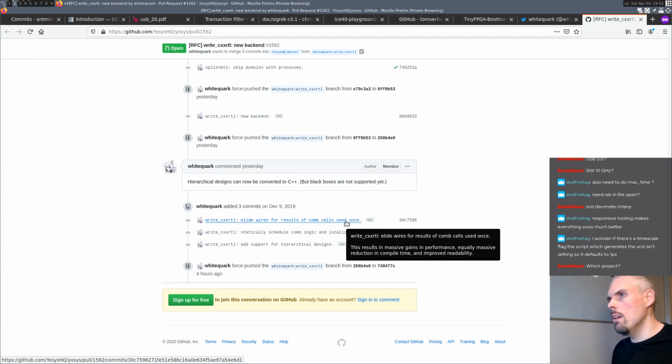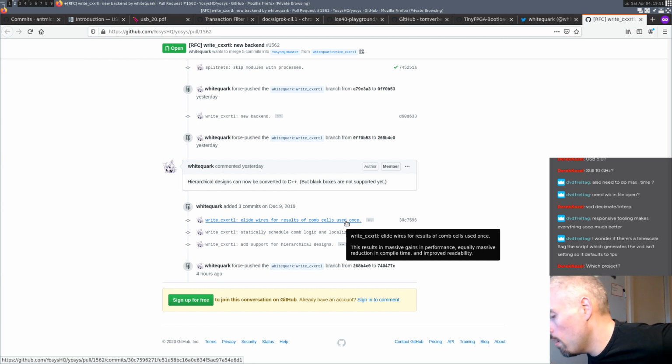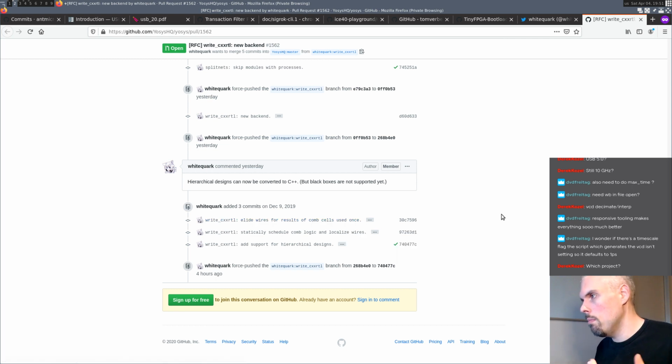It basically uses the Yosys parser and everything, and instead of synthesizing to an FPGA target, it writes the parsed Verilog out as C++ classes with a minimal runtime. Then you can write a C++ test bench that generates the clock edges and the stimulus, and writes the output as you want.